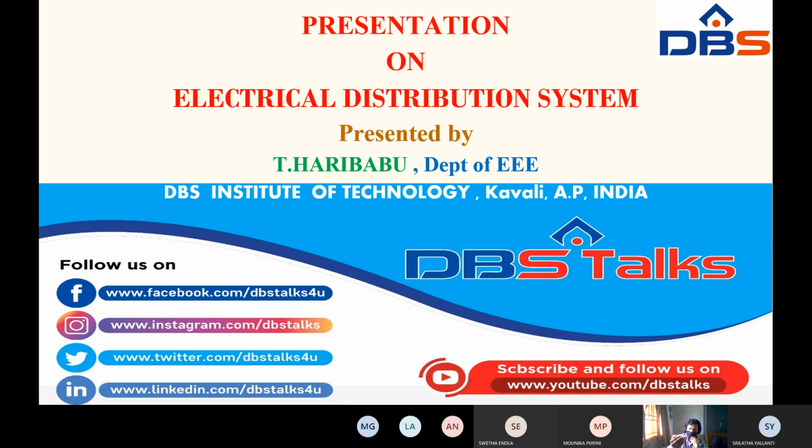From that, to find the annual energy loss, for a year there are 8760 hours. So the annual energy loss or annual copper loss is equal to average power loss multiplied by 8760 per year. That is 12 multiplied by 8760, so that is 105120 kilowatt hour. This is a simple problem, right? All of you note down. Next, second problem.